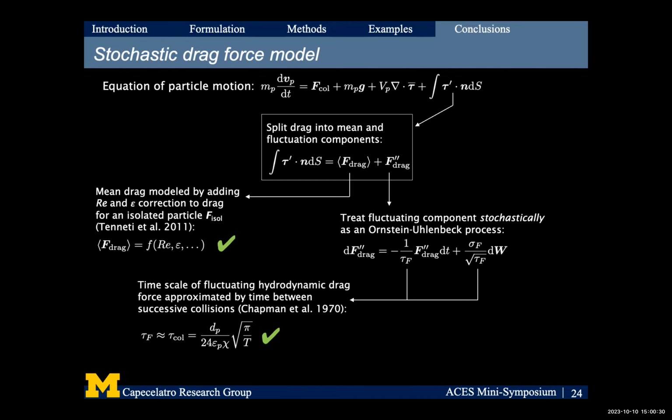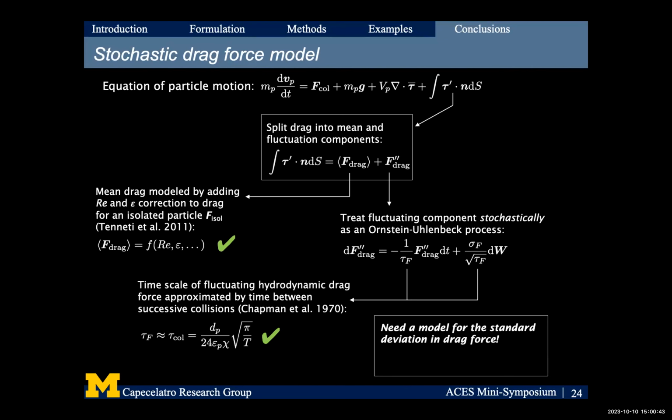The standard deviation, what we did is we took particle resolved calculations, so really expensive simulations where the particles are frozen, not allowed to move. And we just quantified the PDF and figured out the standard deviation as a function of volume fraction. But then we compared it to freely evolving direct numerical simulations. So we weren't tuning parameters here at all, if you know what I mean.